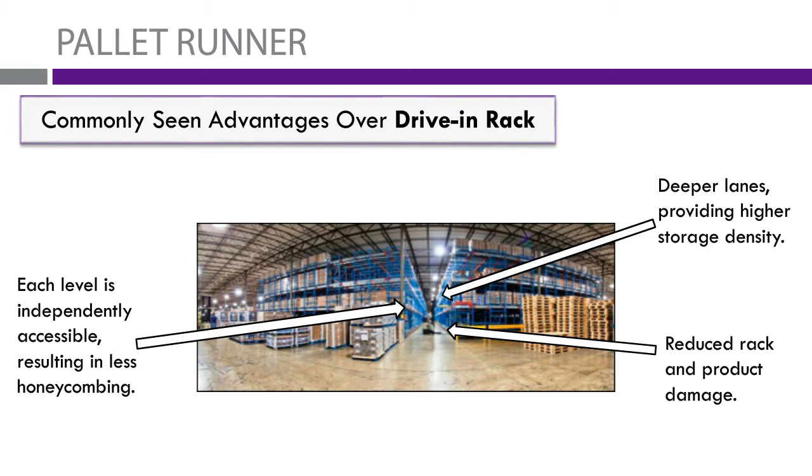So the Pallet Runner brings it right to the front. The really only threat to damage in this kind of system is where they're loading and unloading the pallet in the front, which is easily accessible, makes repairs a lot easier. Again, like I mentioned, when you're dealing with the drive-in, the deeper you go, the more problems you can have. And when you do have damage within the system, it's very hard to reach to repair. It's very hard to access that. And that damage can actually spread in those systems and cause failure.